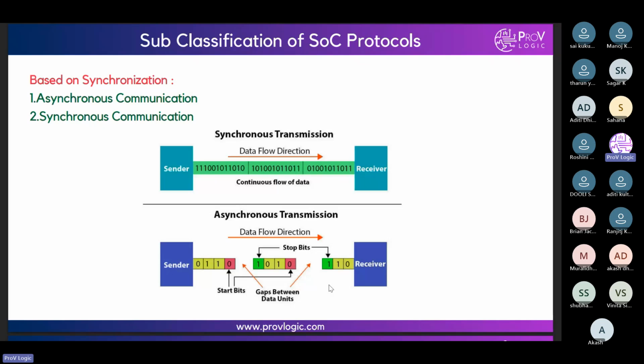Okay, so tomorrow we are going to discuss the baud rate generator also. That means how many bits we can transfer per second. There are a lot of limitations with the baud rate generator, because the transmitter side and receiver side will not work with proper synchronization, and also it is very difficult to connect both the signals, right? So whenever there is a frequency mismatch, a lot of data loss will happen. So here the clock is replaced with a baud rate.